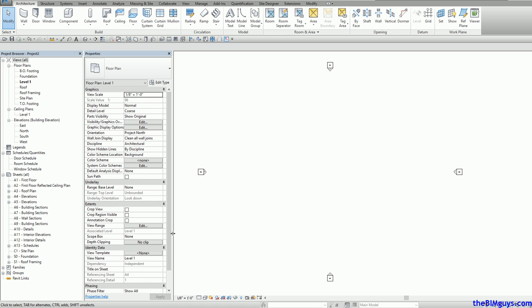Now I'm cutting through the building. Think about this in section, cutting through the building. So you tell the wall to start on level 1, 0, go up to roof. Then we put a roof on it later like this, if you're doing a typical construction. Then we put floors in here, like that. And if you were standing here, that would be you in that location. So we set these levels up so we know how high to bring the walls. And that is how Revit is set up.